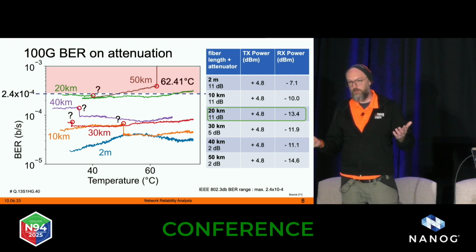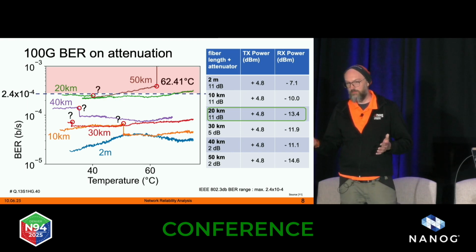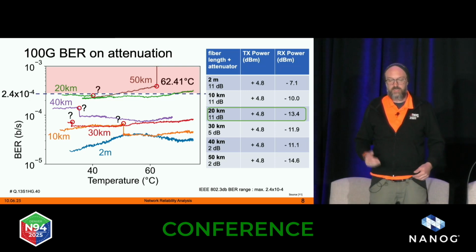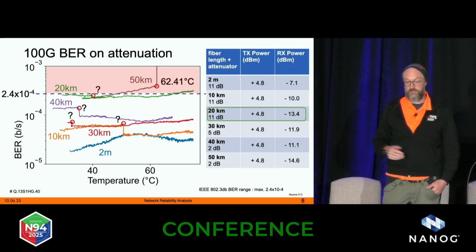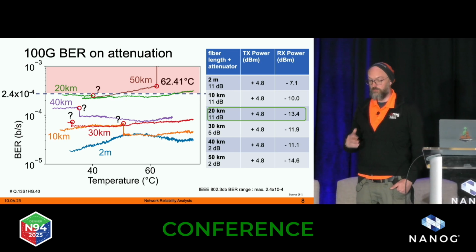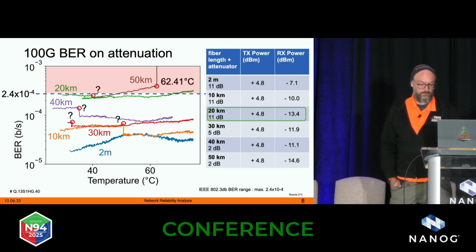In software terminology, it's mainly done in a lookup table. So when we reach a certain temperature, we do some correction on the TX bias current, and then the bit error rate improves, basically. And to sum it up, 50 kilometers was way out of reach because we were also beyond the Rx power minimum.